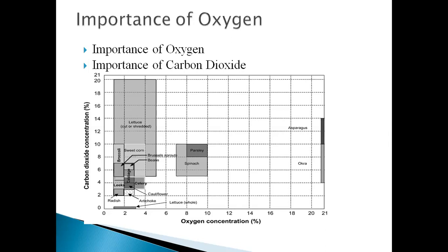Concentrations of carbon dioxide above 1 to 5% by volume can cause fruit decay, irregular ripening, and development of bad odors in storage or ripening rooms. If carbon dioxide levels rise above 7% by volume, it prevents the ripening of fruits by decreasing the production of ethylene. The optimum combination of carbon dioxide and oxygen will depend on the fruit type.